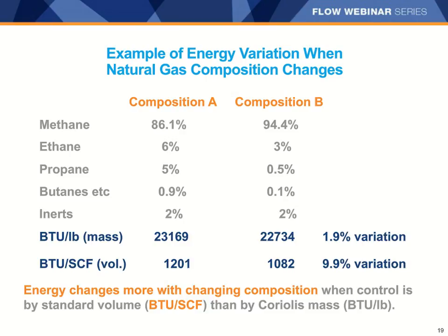Okay, and looks like we're getting some pretty good response here. I'm going to share the results with everyone now. So you can see there's a growing use of Coriolis meters at about 9%, but as I would have expected, differential pressure is by far the most common. And the obvious reason for that is because differential pressure meters and orifice meters have been used longer than any other technology. They're very well understood and are basically the de facto standard and have been for many, many years.